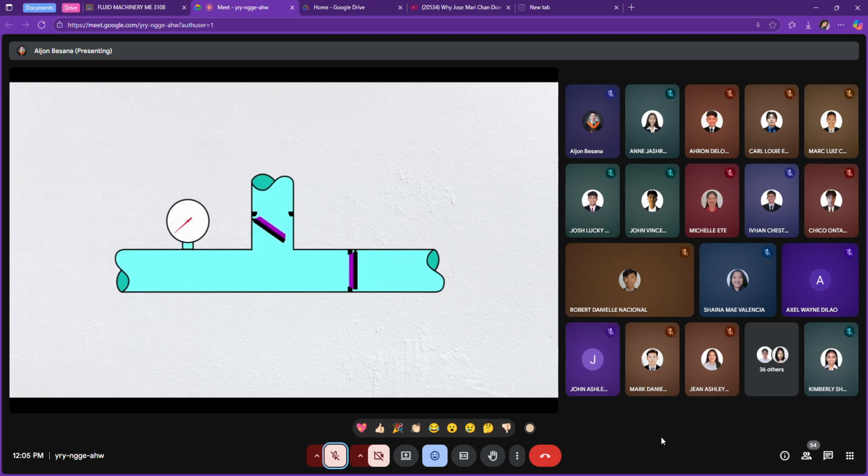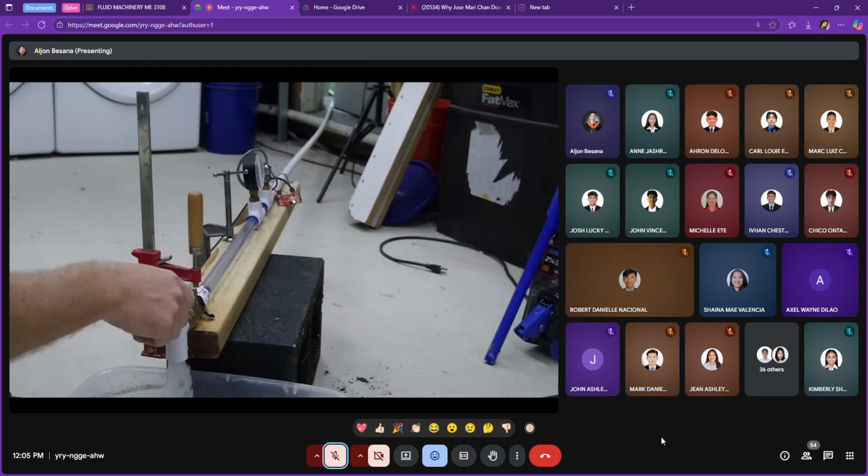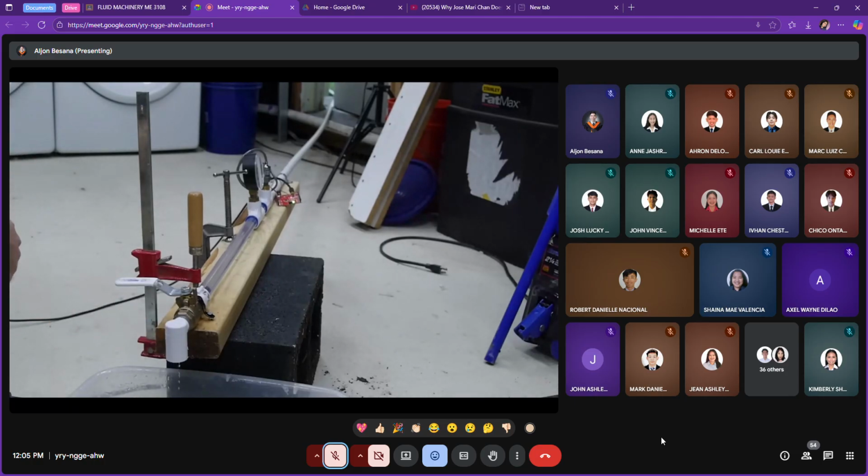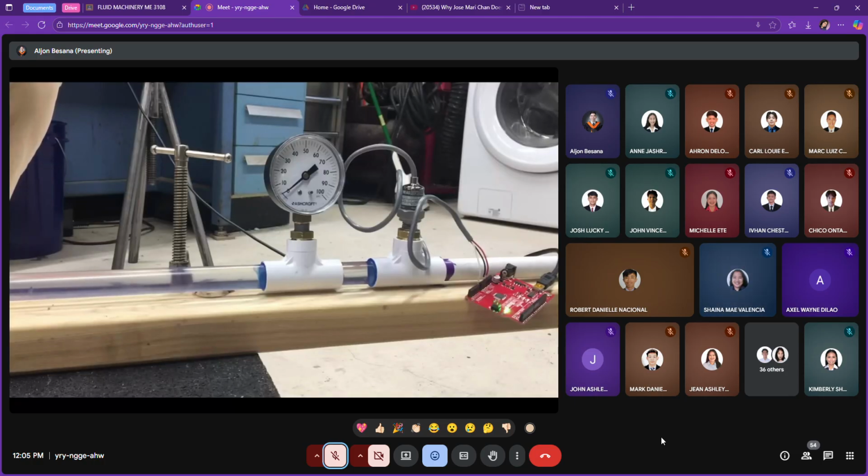That means the kinetic energy was converted to something else, in this case, pressure. This is the definition of water hammer. Slamming a valve shut converts all the kinetic energy nearly instantly, creating a huge spike in pressure that can lead to stress and damage in pipe systems and connected equipment.